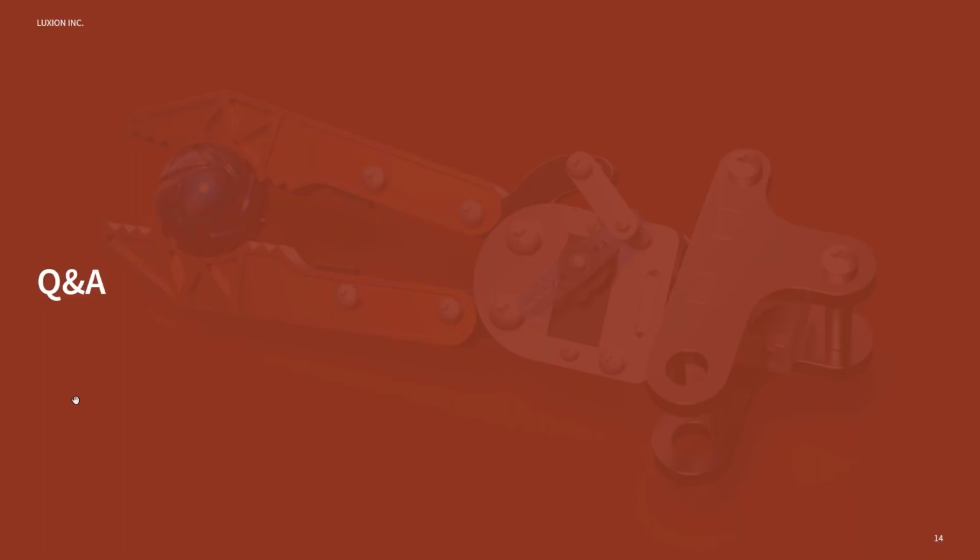Immediately my mind went to material templates, but I don't know if you have any other recommendations that may be similar. Yeah, I think material templates sounds like it'd be the way to go if you're managing a custom library of materials or appearances inside of SOLIDWORKS. The most efficient process would actually be to have a matching library of materials in KeyShot with the same names, and you'll be able to match those up.